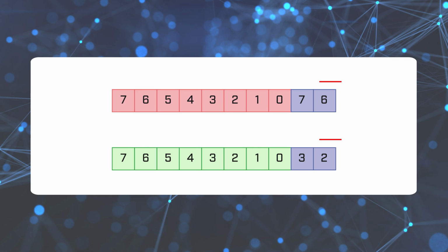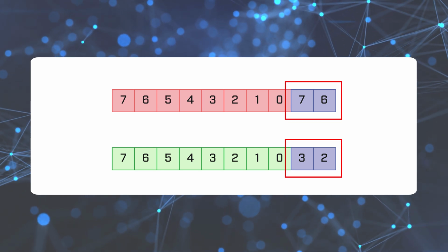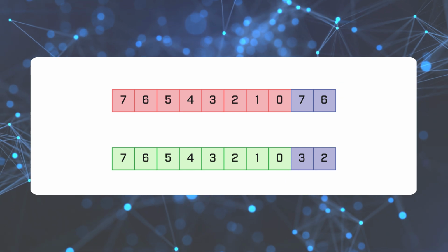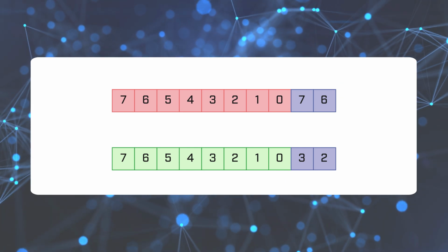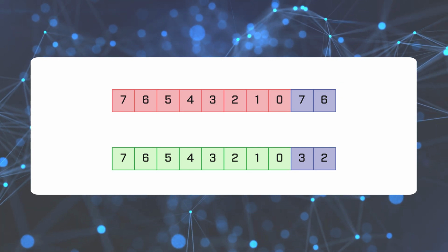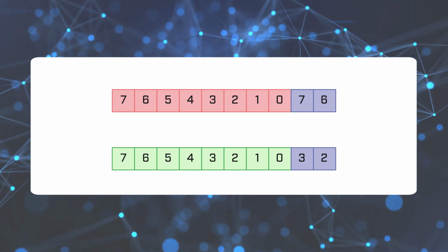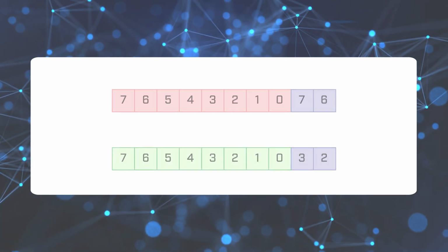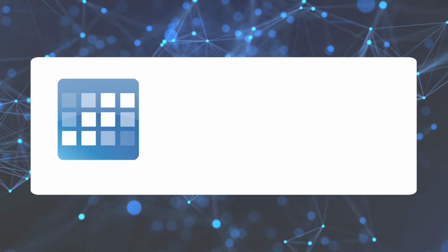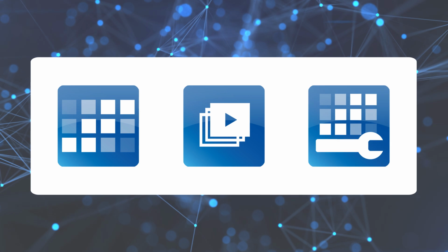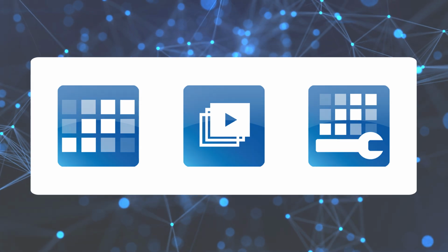At the 10-bit 120 Hz mode, 2 bits of the blue color channel are used in addition to the 8 bits of the red and green channel. To use the 120 Hz mode, your input images or functions must be converted to the required 960 by 1200 pixel input format using the 3 color channels. This is done automatically if you use the HOLOEYE Pattern Generator software, the SLM Slideshow Player software, or the SLM Display SDK. The SLM is now properly configured.